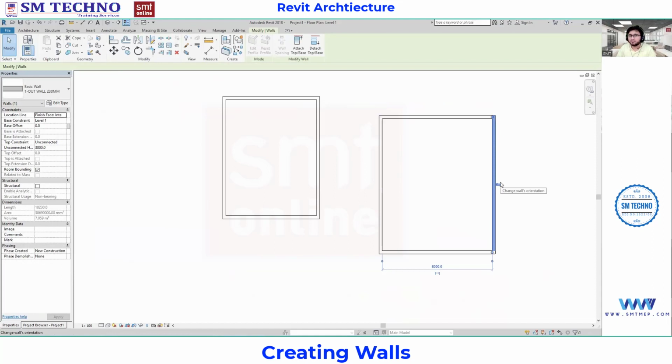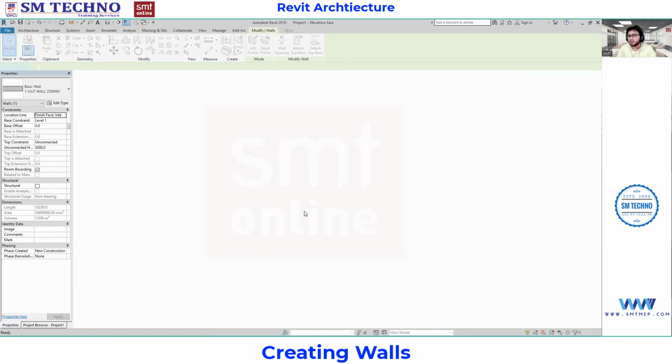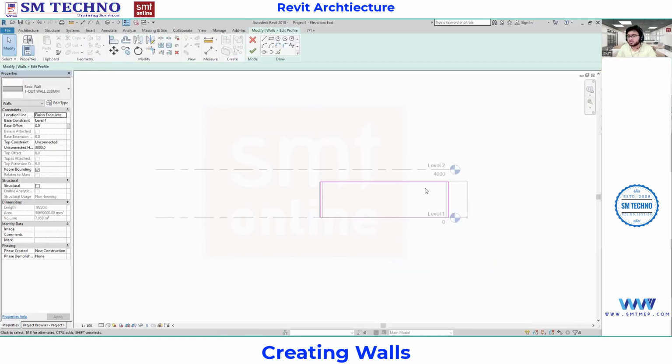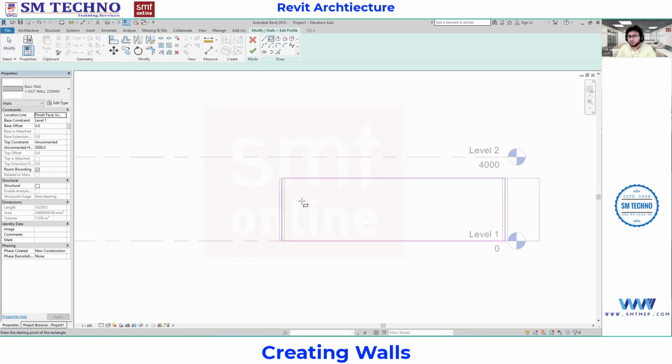So select this one. Can you see in the Modify Walls, in the Mode panel, the Edit Profile option? So go for Edit Profile. This wall is visible in the east or west view. So open any view. I'm going with east. Click here, open. So now you can see we have got the east elevation. In this sketch, whatever you want to sketch, like any kind of open window, you can provide a mark over here, or any kind of arc.